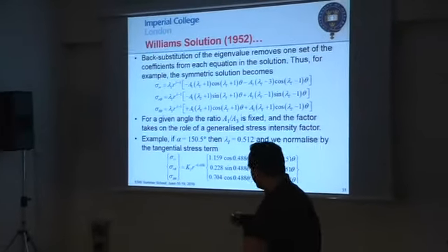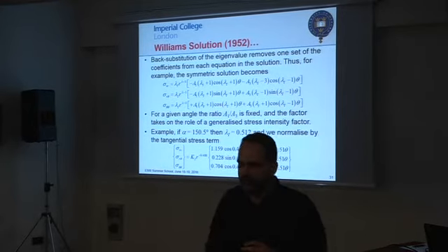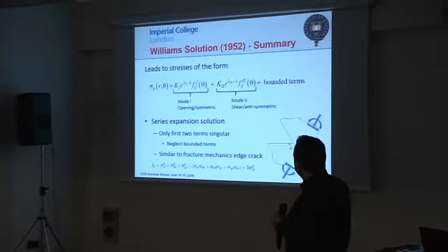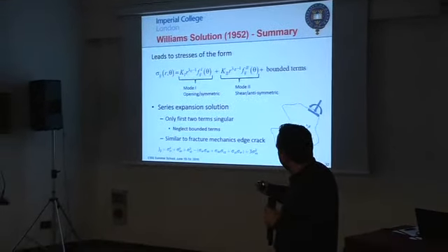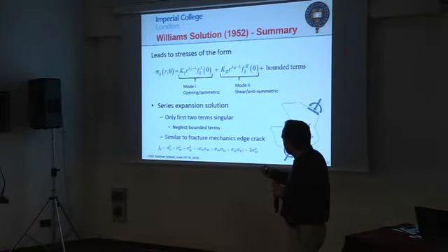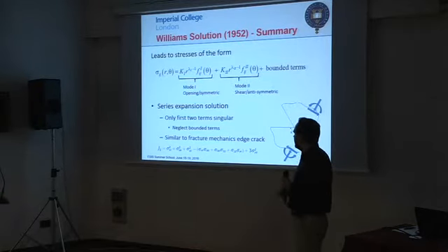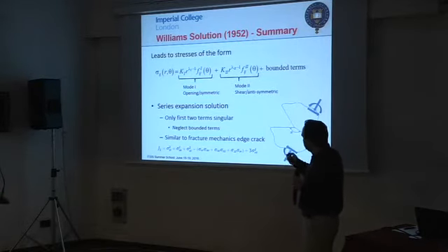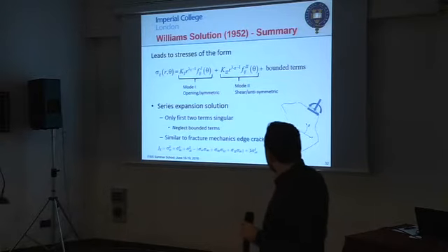And obviously, K1 and K2 will depend on the remote load, and we're going to go back to how to compute those later. So, therefore, I can write stresses in this form. I can write any component of stress as a term given by mode 1, K1 r to the lambda 1 minus 1 by a function of theta, f1, plus the mode 2 term, which is K2 r to the lambda 2 minus 1 by a function of theta, f2, plus other terms.